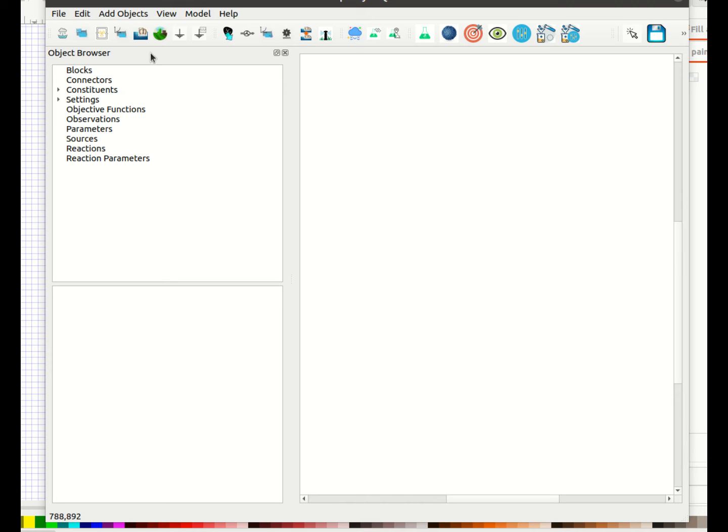essentially in effect. The other thing that we need to have is that any link that we use, that we want settling to happen through, should have an area. Okay, so basically, not all links have a property called area. So if you have a link that doesn't have area, you're going to get a warning. The model will still run, but settling will not happen through those links.